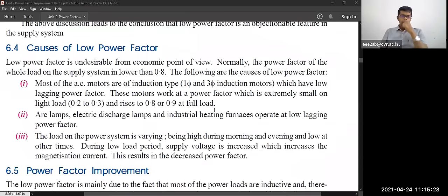If you are using a welding machine on a single phase supply in the peak hours, sometimes neighbors nearby will feel less voltage. Sometimes appliances in nearby houses will misbehave. That will be monitored in domestic lines. If the power factor is being maintained low, that will be monitored by the substation also.